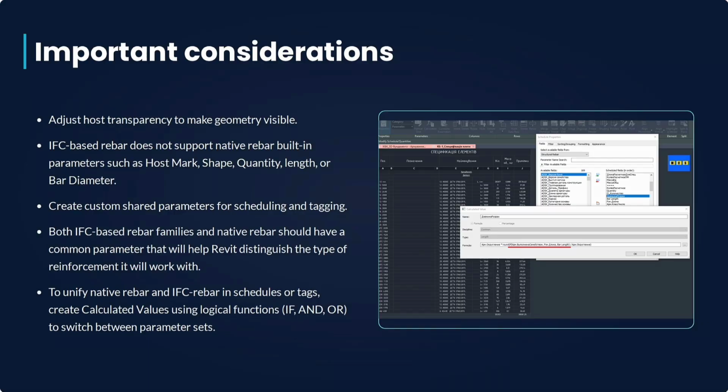Also, both IFC-based rebar families and native rebar should have a common parameter that will help Revit distinguish the type of reinforcement. To unify native rebar and IFC rebar in schedules or tags, you must create calculated values using logical functions, IF, AND, OR, to switch between parameter sets.